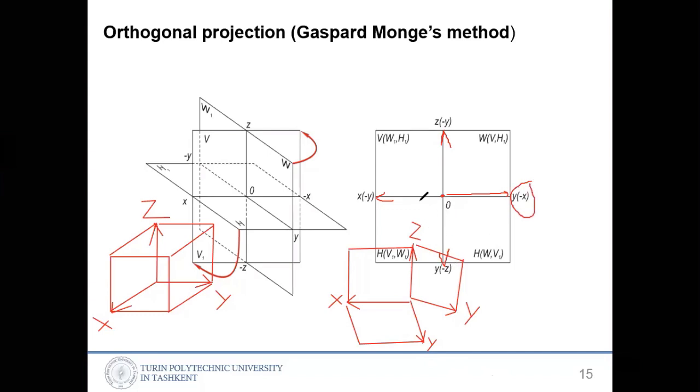So when you draw anything here and measure this distance, here also will be the same distance, because that's the same thing. So when you draw something, you can measure and make the same drawing like this, and then you can intersect and generate the third one. If you have a two-dimensional shape, or two projections, the third projection you can generate using these two projections. The front view projection and top view projection are given, so the right or left-hand side view projection can be generated using front and top.